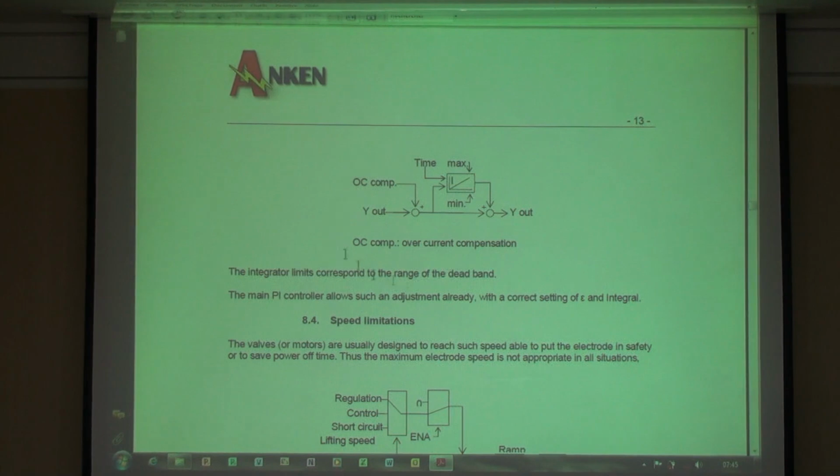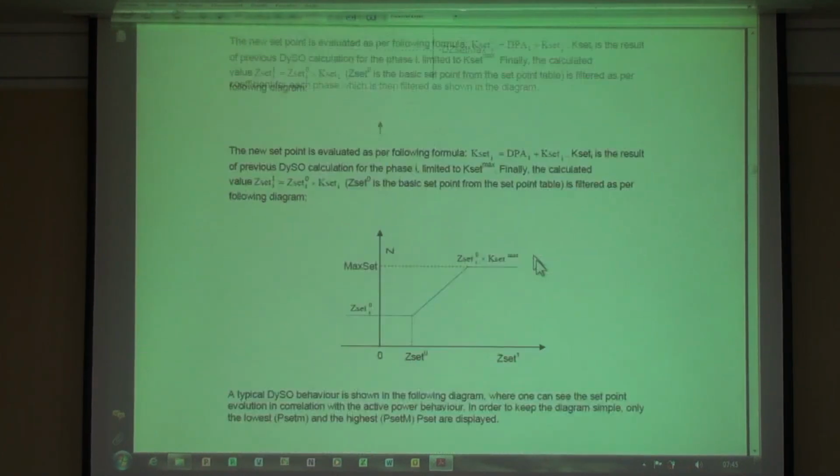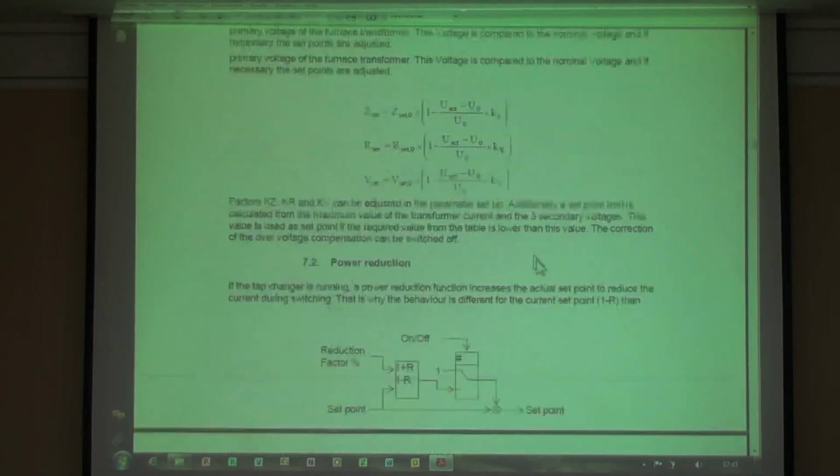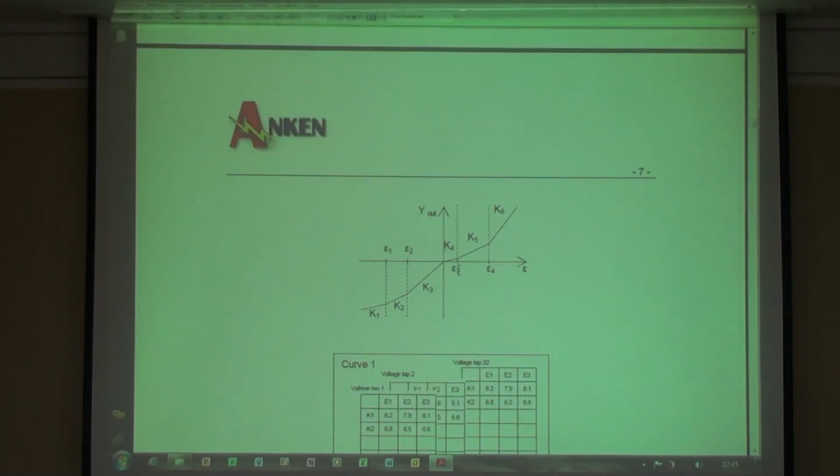And you don't need to have a special function, as we don't have a linear PI controller. So if I go back here, if you have deadband, we can adjust this threshold and this coefficient to compensate the deadband, to have a large proportional coefficient here in this area.